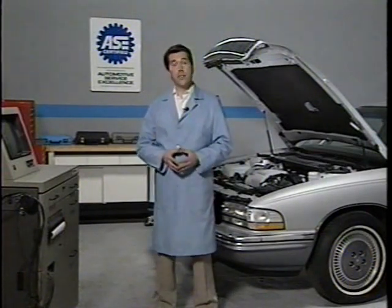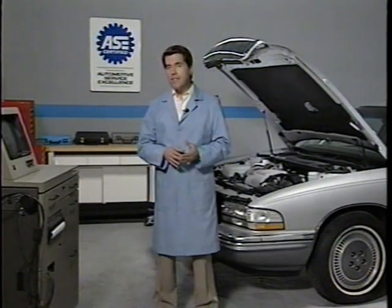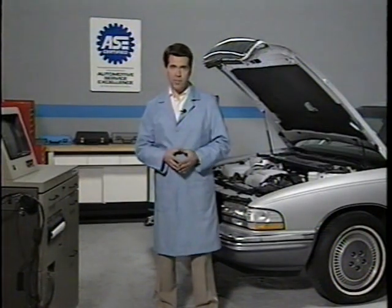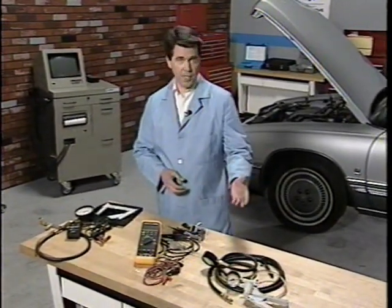As mentioned earlier and shown in the general symptom diagnosis chart, to solve drivability problems, you must understand how the ECM-PCM and its components operate, as well as their relationship to the other three engine systems. In many cases, you start your diagnosis of a drivability complaint by running some systematic tests on the three basic engine systems. These include fuel tests, ignition tests, and compression tests.